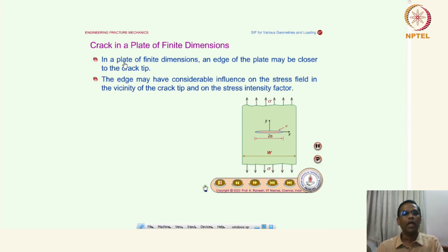Here, in a plate of finite dimensions, an edge of the plate may be closer to the crack tip. Whether it is close to the edge or not is the question, because that will influence the stresses. The edge may have considerable influence on the stress field in the vicinity of the crack tip and also on the stress intensity factor. So that is what is shown here.